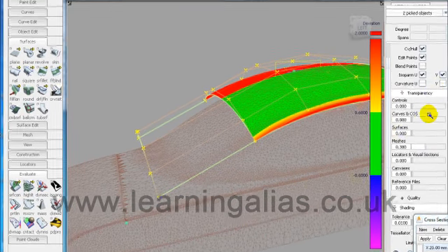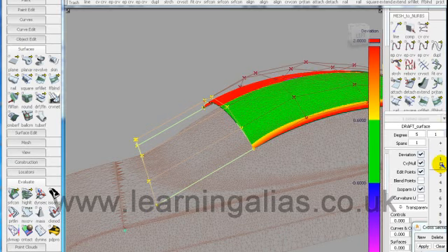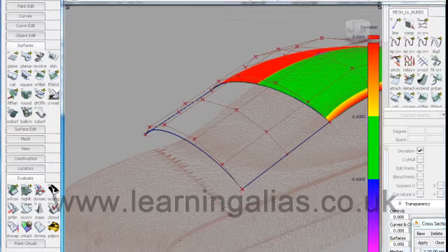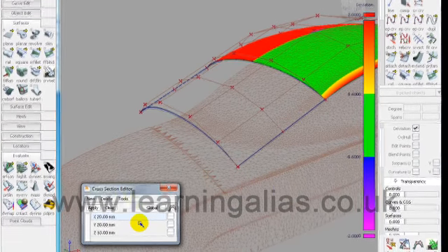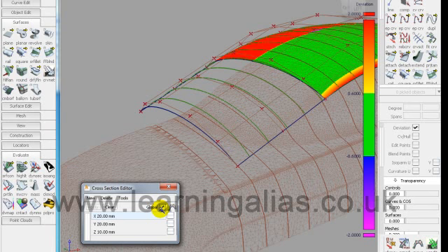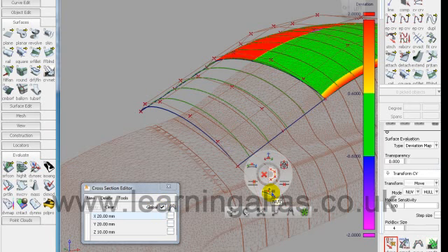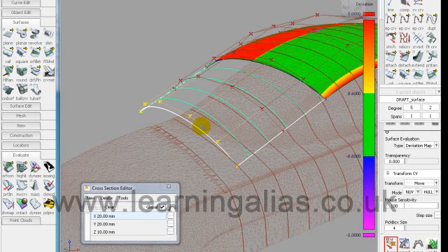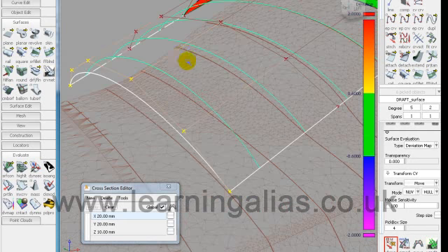So come over here in the control panel. Let's do it this time with cross sections. There we are. I'm going to use NUV here because of the angle. If I use XYZ, it would stretch the surface and change the configuration of the CV HUDs, which I don't really want to do. So I've picked that. I'm going to just pull that down, and let's zoom in a bit, and we're looking at this zone here. I'm not concerned about what's happening at the edges at the moment.